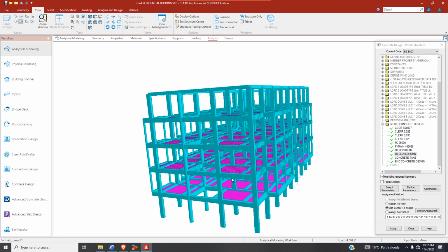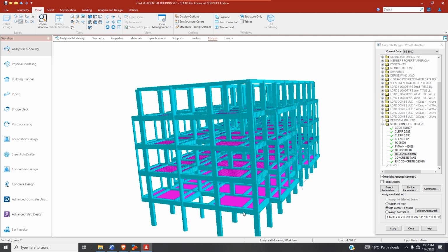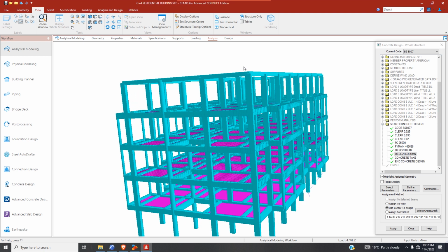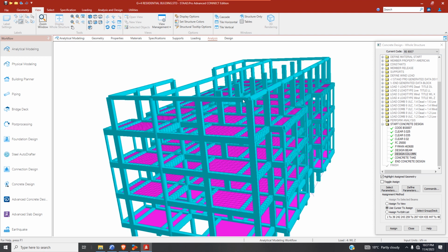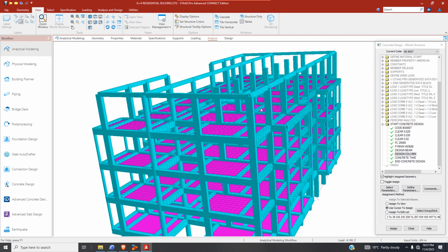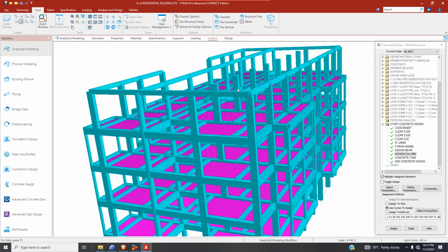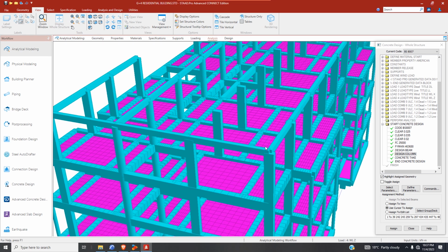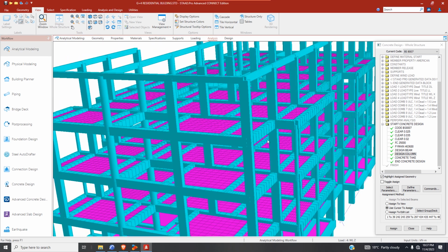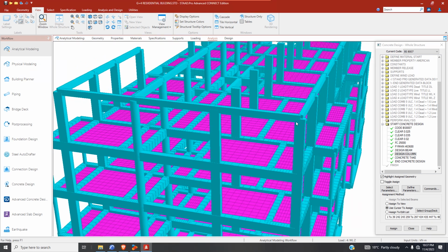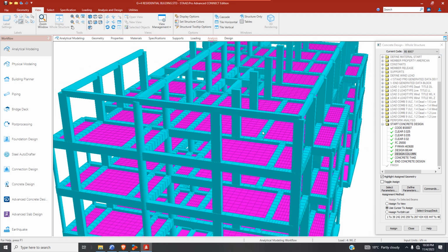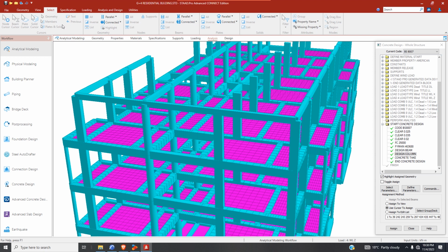So go to this view. So we go to support, we must add the support. So you have to remove this because this one is out. Code, so create fixed and select all those nodes. Assign yes, then save, and run analysis, run, check for zero errors.